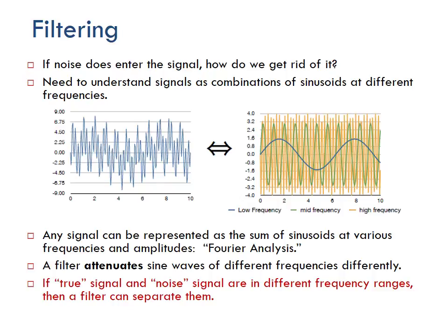Likewise, a low pass filter is going to get rid of all that high frequency yellow and probably a lot of the green too, and it's just going to let your blue show through. And then a band pass filter takes some band in between a high frequency and a low frequency, and lets me look at that mid frequency, the green one. So these are all different strategies to let us look at individual signals that come out of a more complex thing.